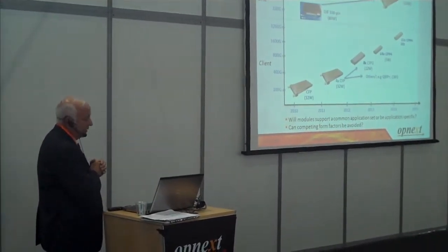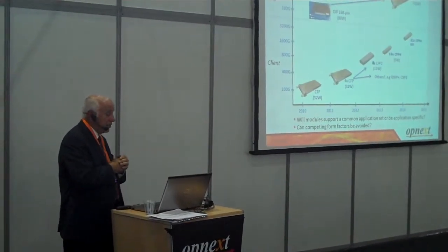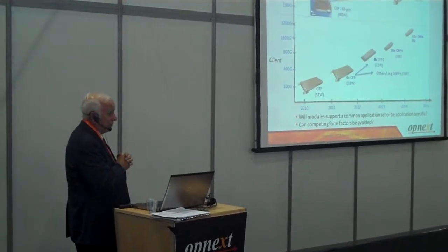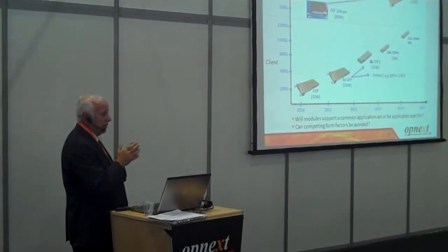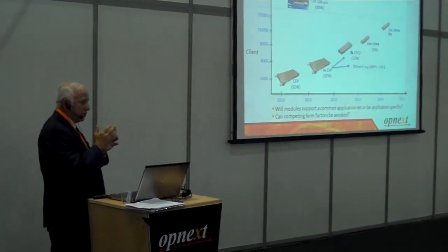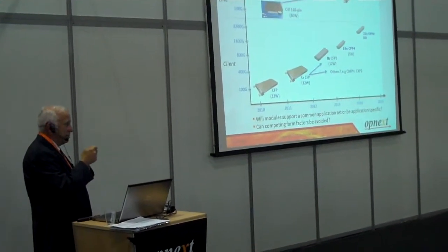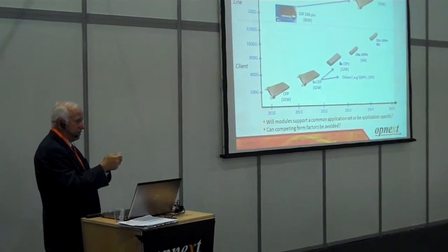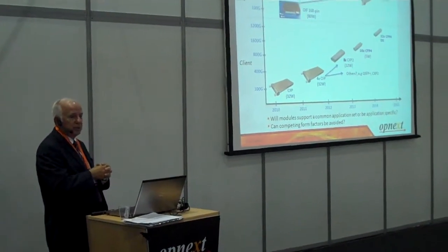On the line side right now, we see it going into a pluggable, into a CFP package, but quite frankly, it's not here today because these are 80-watt type designs. There's a lot of power, and they have to come down as the technology evolves. But this is the first time, in a 100G coherent design, that we used to design optical networks with brute force optics: how much can I get out of the optics? These designs are based on digital trade-offs with the optics designs to optimize it. So you get much better performance, and then you're on a digital curve to reduce the cost.